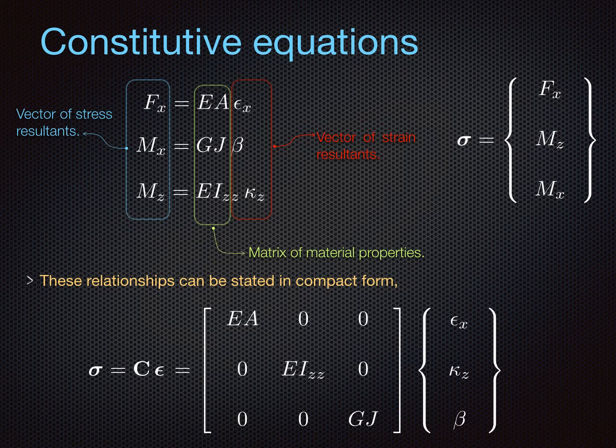And also I'd like to note that while this constitutive relationship is uncoupled here, this still does not mean that in any given problem we will have an uncoupled axial problem, an uncoupled torsion problem and an uncoupled flexural problem. Through the geometry of the problem and the boundary conditions, all of these problems may well be coupled, even if the coupling does not exist at the constitutive level. Imagine a portal frame.